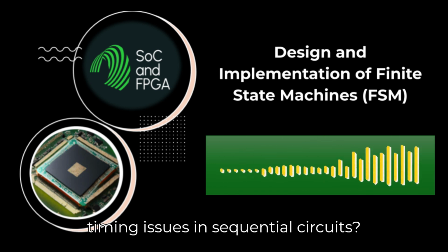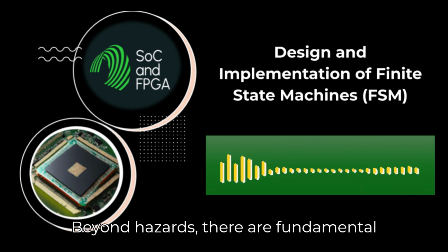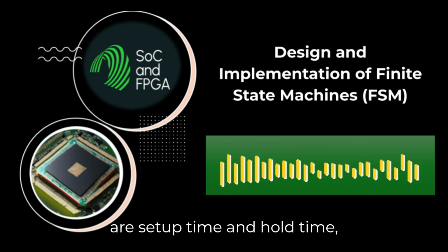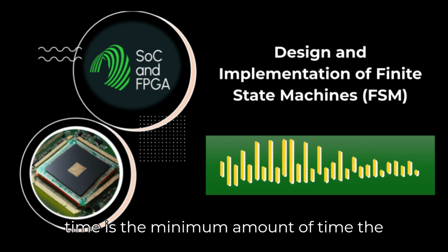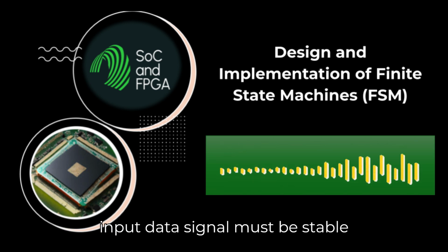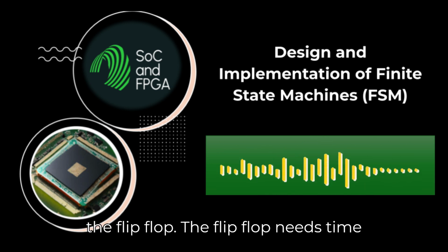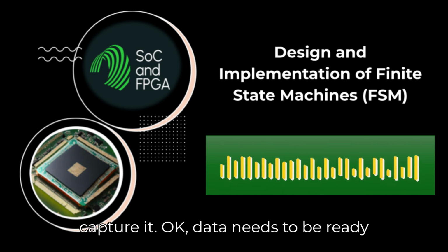What about other timing issues in sequential circuits? Beyond hazards, there are fundamental timing rules that must be met for reliable operation. The most critical are setup time and hold time. Setup and hold. Heard those terms. Setup time is the minimum amount of time the input data signal must be stable before the active clock edge arrives at the flip-flop. The flip-flop needs time to see the data before it tries to capture it. Okay, data needs to be ready early.